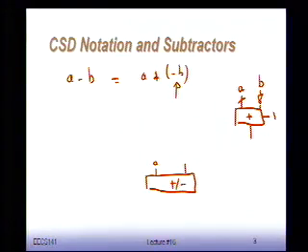So I add a second input B, but instead of using an inverter here, I'm going to use an XOR, which has B as input, and plus minus. And then I use also plus minus as the other input. Plus minus is the choice between doing addition or subtraction. When it's an addition, we just set it to 0. When it's a subtraction, we set it to 1. So in that case, the carry in is going to be 0 for an addition, and 1 for a subtraction.